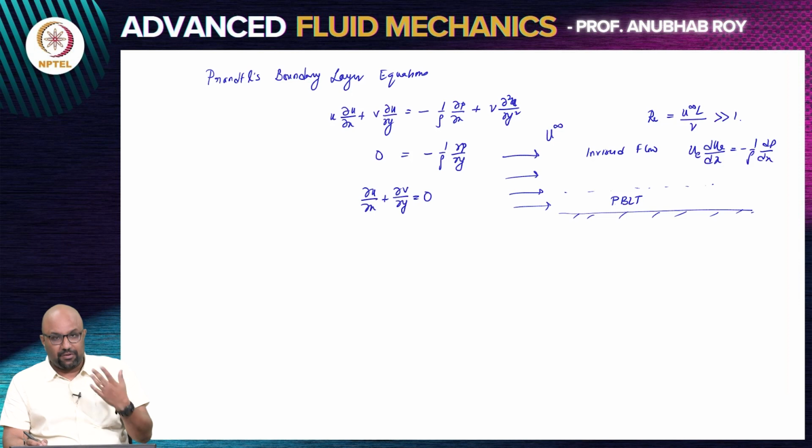Now, we also saw different measures of boundary layer thickness in the previous lecture. We saw one based on displacement of streamline, we saw one based on the resisting force that is given by the surface, so that is a momentum thickness, and you could also work out similar measures based on losses of energy, kinetic energy and things of that sort. You can also have an empirical measure by saying that the location where it is around 99% of the incident flow, that is basically my location of boundary layer.